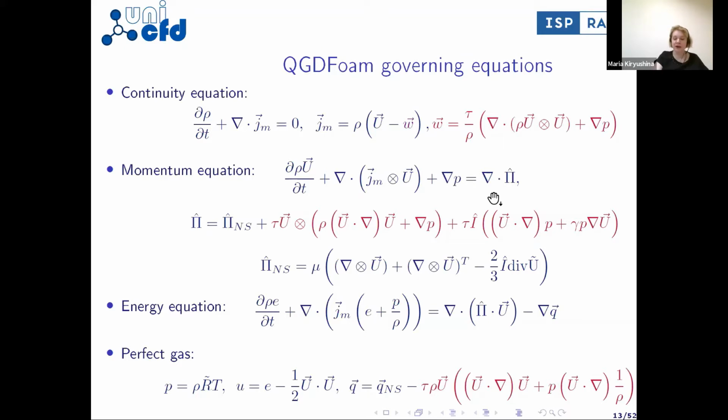These regularized equations are approximated using entropy preserving schemes. And regularization terms are calculated in half points. Regularization terms in OpenFOAM on face centers can be calculated in two ways.